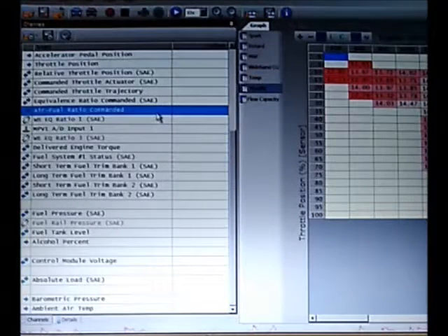That's normally the way you would tune, except in our case we're going to do something a little special. We're going to customize our own sort of matrix that's going to have all the desirable air-fuel ratios that we are going to design from scratch, and then we're going to use that to compare against the actual AFR. So this is kind of an optional thing too.